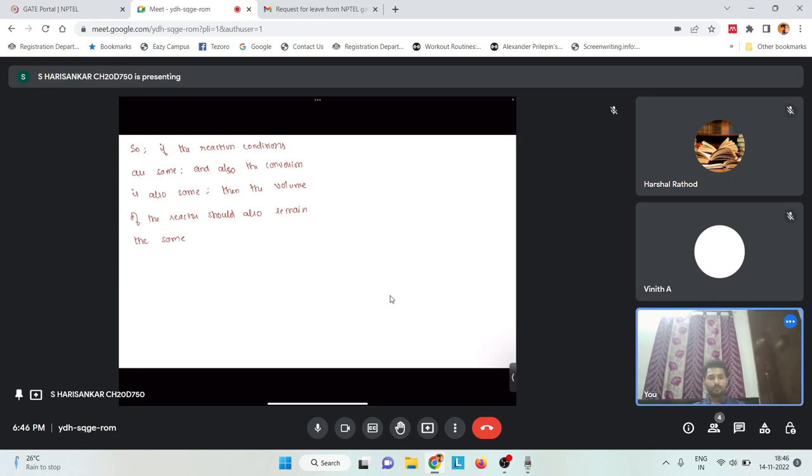Okay, so using this, we'll try to see how we can proceed. So first, what we need to find here is the volume of the reactor, volume of our plug flow reactor, and it is given in the question that this plug flow reactor is made of 7 stainless steel pipes of 6000 millimeter length. So volume of this PFR will be 7 into volume of 6000 mm long pipes.